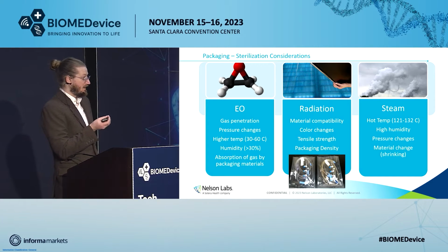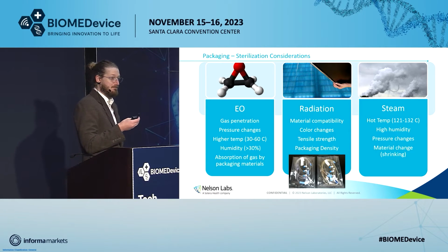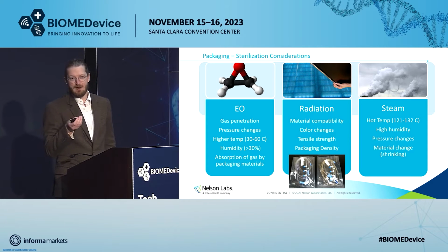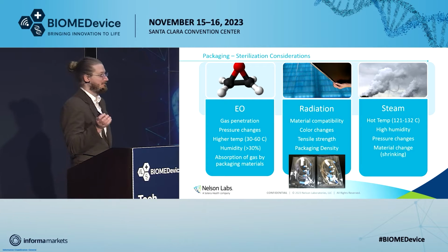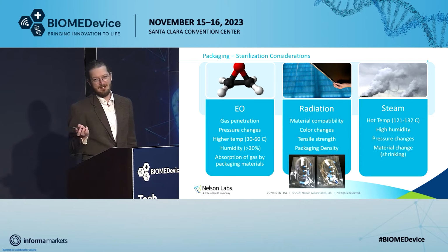So the risk there is that after you perform radiation sterilization and your poly pouch now becomes embrittled, perhaps now it's no longer going to maintain its integrity and it'll break or shear or shatter apart, and now microbes can come in and all of your sterilization is completely undone, right?